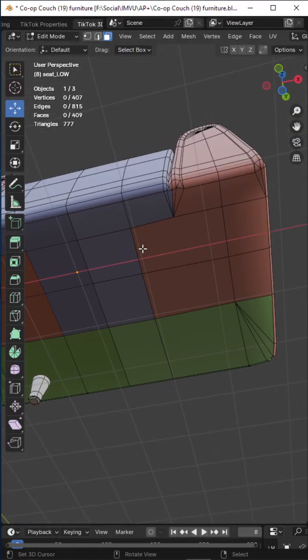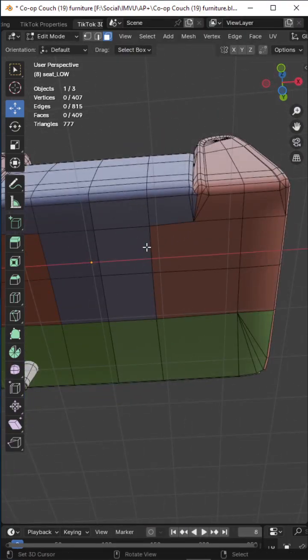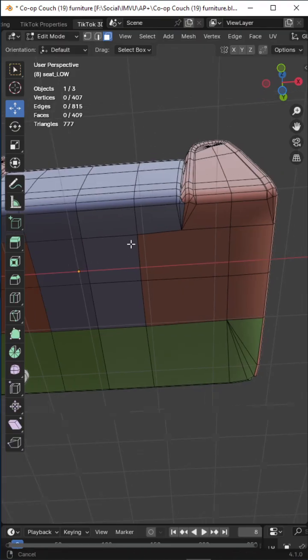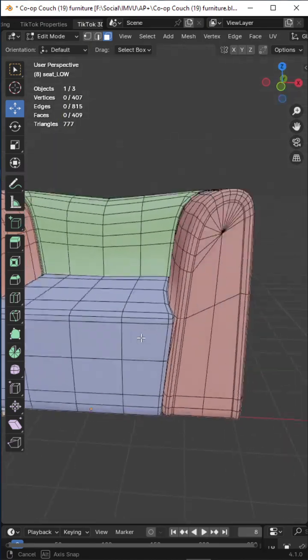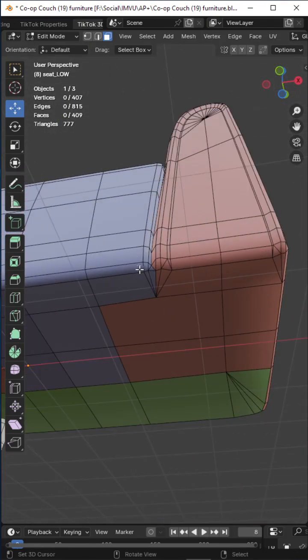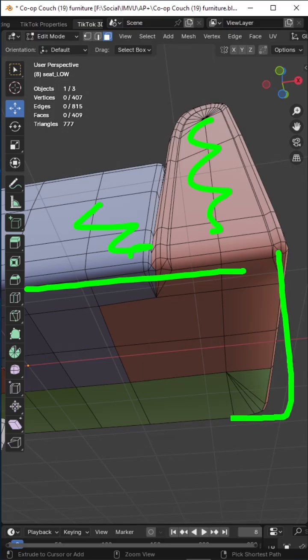What we want to do here as well, so when we're UV mapping, we've got a couple of options. You can either unwrap the entire object and basically use the same image on each section, and it will have the same density, so the same amount of detail, but for areas that are not seen, that's wasteful.